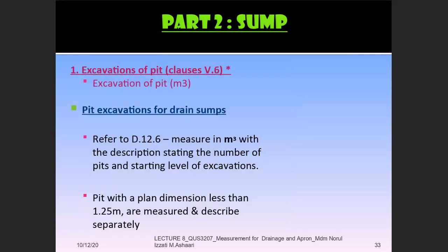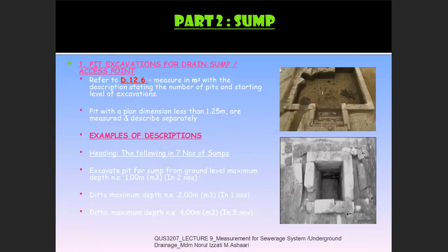In case you forget how to write down the description for the pit excavation, you can refer to D.12.6, measured in meter cube by stating the length on plan, whether it is less than 1.5 meter or more than that, stating the starting level and the depth of excavation. Okay, so the depth of excavation, maximum depth, you can refer to D.10 and starting level under D.11. This is also another example. Okay, as what I did mention to you.